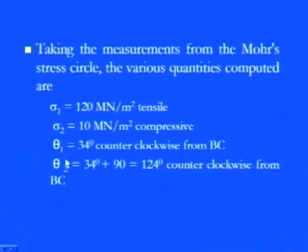And again, because the 2 theta is there for AB bar to BC bar, you can again calculate the theta 1, that is 34 degrees, the positive direction because it is clockwise from the BC. And then theta 2 always comes by adding the 90 degrees for the next principal plane location. So 34 degrees plus 90 degrees, 124 degrees counterclockwise from the BC.